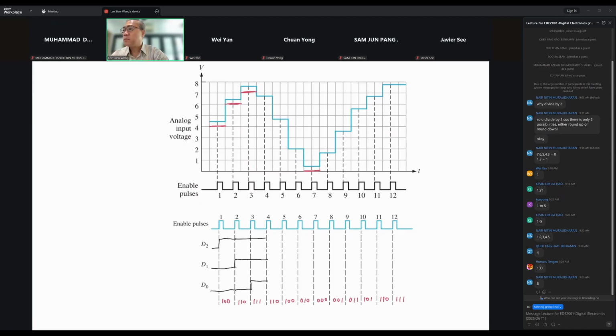The next one has a little bit more intelligence built in. The other one is pretty much brute force. You have one entire row of comparators, then just compare, then after that use an encoder to come out with the output. So the next one that comes is a very smart usage of an ADC. It's a very smart design.